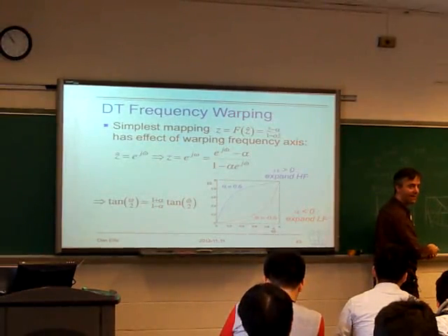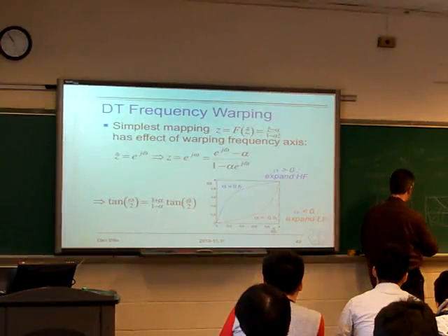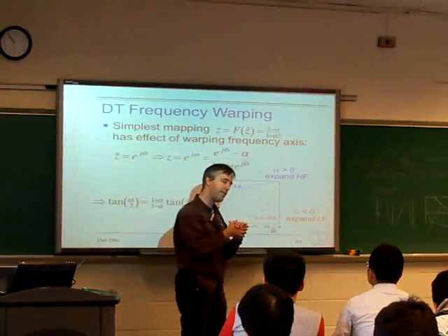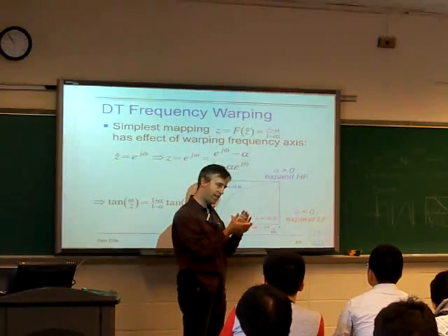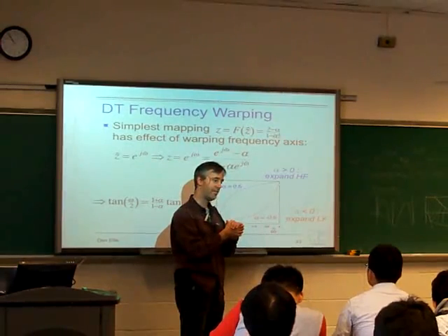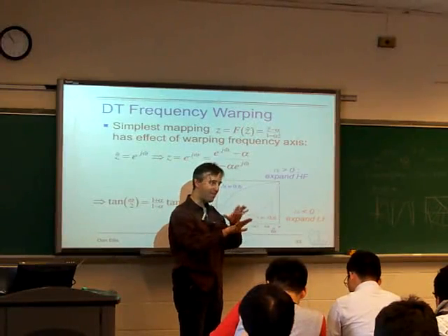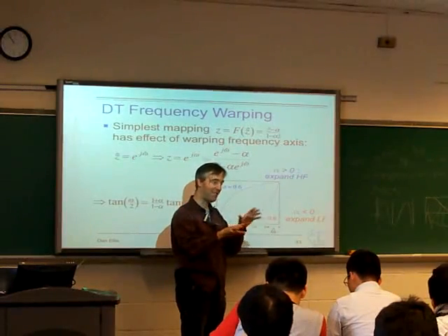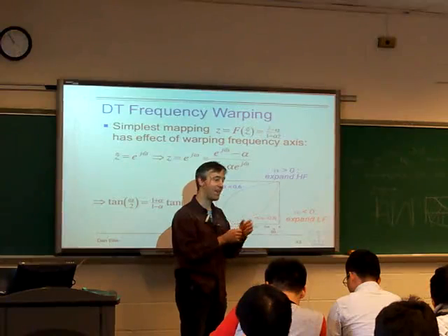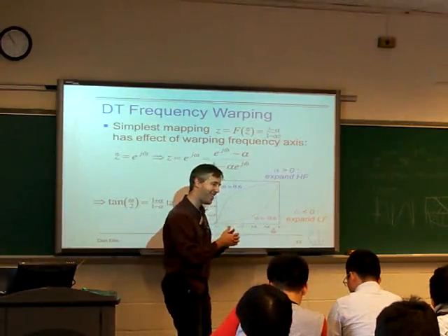But the warping, what we are doing is to the magnitude response, right? No, it's to the entire thing. It's just to the values on the z-plane, right? We're just changing where on the z-plane these values line up, and so the magnitudes are the same and the phases are the same. It's just that the frequencies at which they occur are different. That's the whole notion of this plane mapping business. That it's a one-to-one mapping of every point on the z-plane, and so whatever the properties were at that point on the original plane, you get the same properties in the mapped plane. Okay.